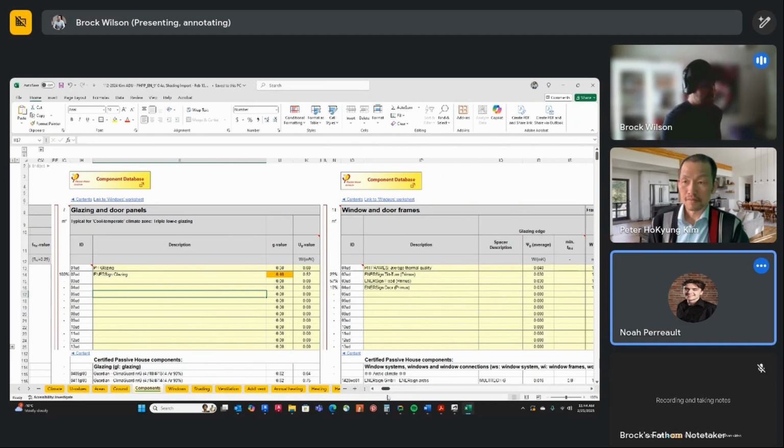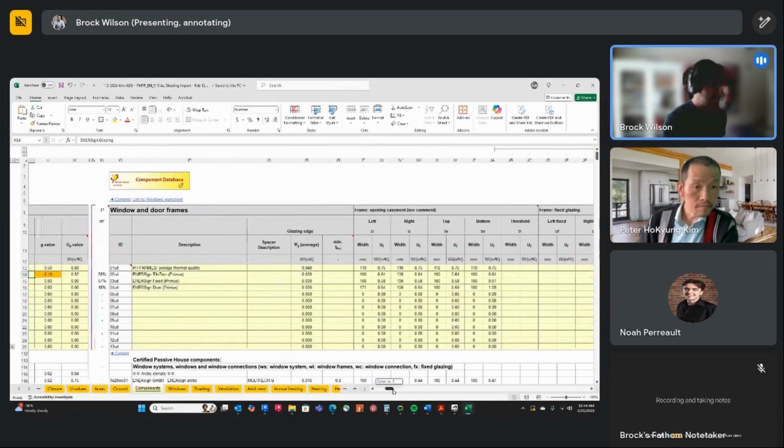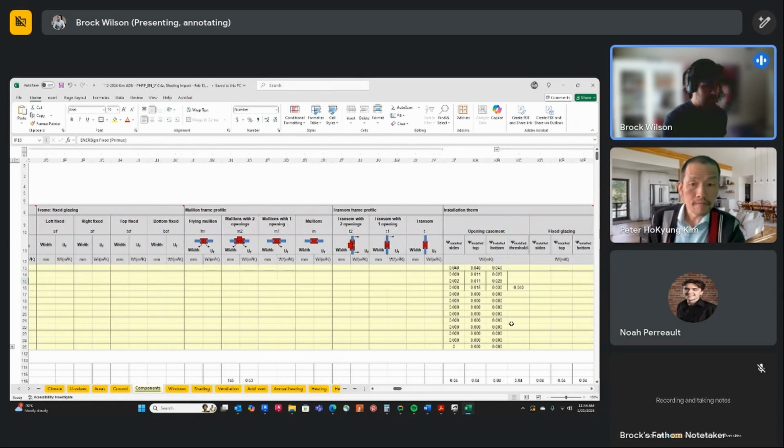So yeah, exactly. In terms of glazing, we've utilized EnerScience glazing, with G values and U values specific, and all of their appropriate data and information for their frame components. We've also inputted the thermal bridge values from the EnerScience certification, based on the specific wall assembly.